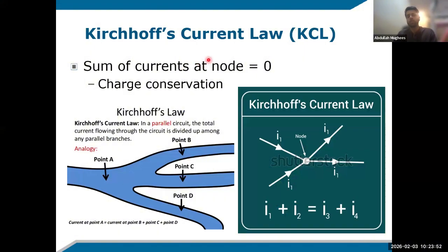What Kirchhoff's current law says is that if we have a node, which is a point somewhere in the circuit, let's say this red dot that I'm pointing at is that node, then all currents entering that node are equal to all currents leaving that node. So there are no losses, no sudden absorption of energy from the circuit, and no sudden induction of energy from outer space into our circuit. Instead we have a simple thing that we can see in rivers as well.